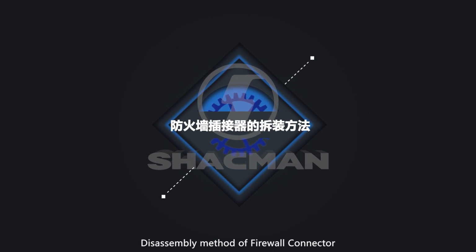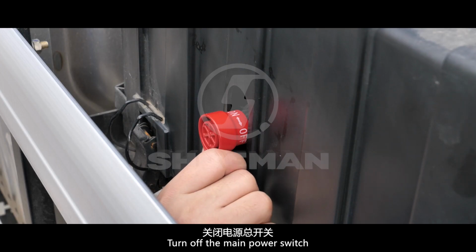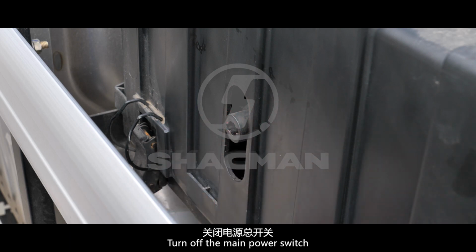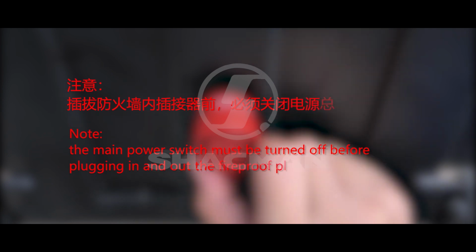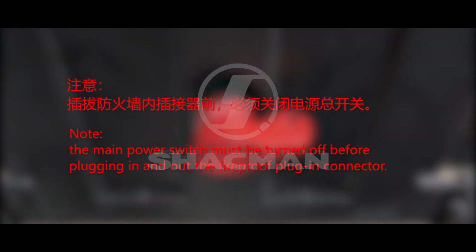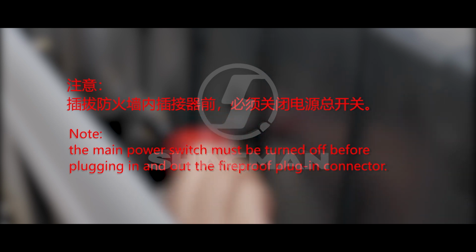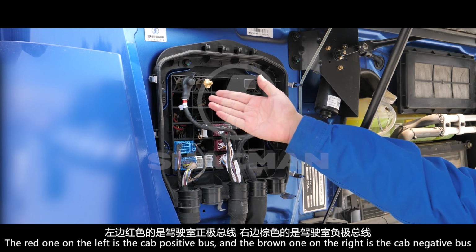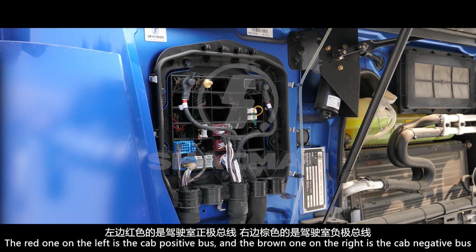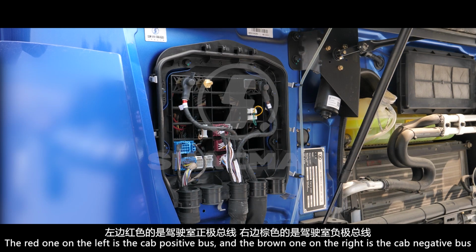Disassembly method of firewall connector. Turn off the main power switch. Note: the main power switch must be turned off before plugging in and out the fireproof plug-in connector. The red one on the left is the cab positive bus, and the brown one on the right side is the cab negative bus.